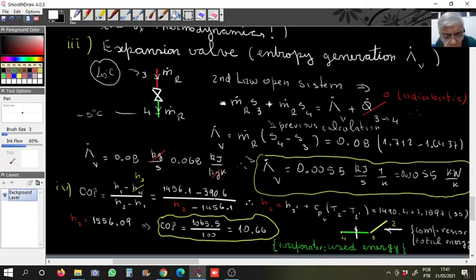Okay, then I multiply over here, and then I have this is the answer. Okay, point double O here, 55 kilowatt by Kelvin. Okay, attention now, kilowatt by Kelvin. Kilowatt is kilojoule divided by second. See, this is kilowatt, and this is divided by Kelvin over here.